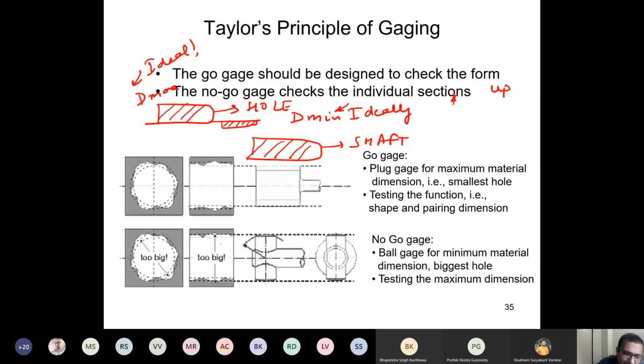Yes. So I would rather reject some pieces, make very tight tolerances here. So this will be the tolerance on my go gauge. On my no go gauge, again I will go the other way around, I'll come down. So in this case, in both go and no go gauge, I'm rejecting some good pieces, but I'm not accepting any bad piece.